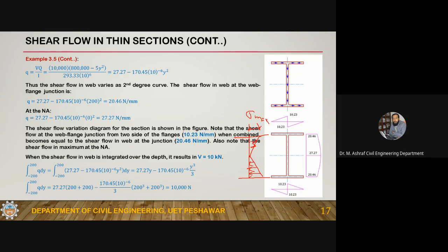Let's suppose the shear strength of a steel is equal to 30 ksi. So this is the strength. If you are increasing the thickness, what will happen? The shear stresses will get decreased, and that is good for the shear. If the shear stresses are decreased and the shear strength is high, this is good. Strength is high and stress is the demand. So your capacity is higher and your demand is less.